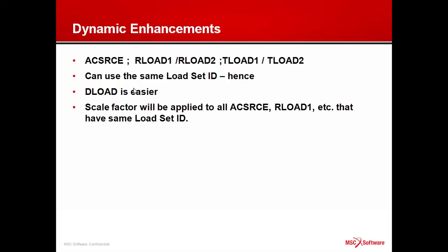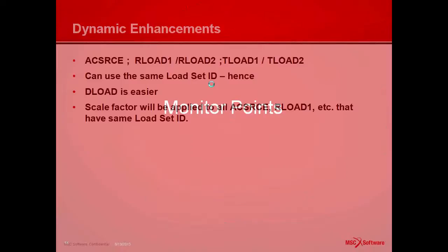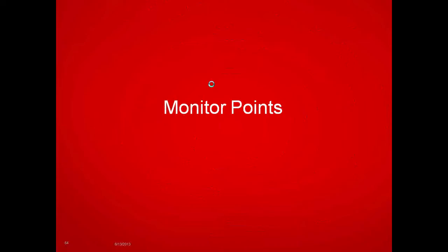So now what you can do is give the same load set ID to all your load options, and then the deload option is easier. Also, if you're using different scale factors on these loads, you can apply the same scale factor for all the loads which have the same load set ID. So that makes life easier as well.